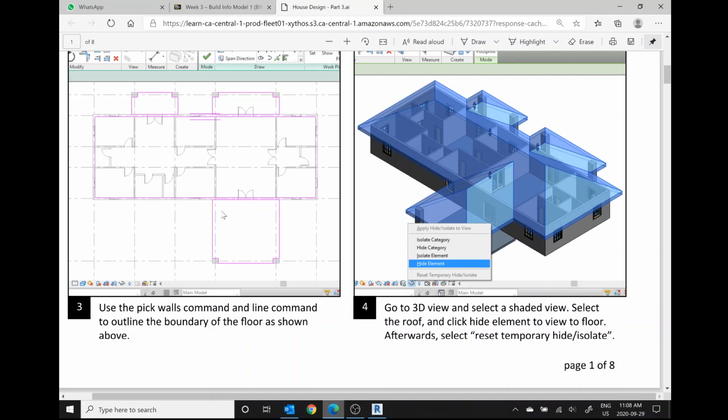Now from a construction point of view that makes sense, because the exterior ones are going to be subject to freeze-thaw cycles. So the ground is going to shift up or down a little bit based on how the water is freezing in the soil. And even if that's only 1 or 2 centimeters up or down, it's enough to crack concrete if it's attached to something that isn't moving. Even 1 or 2 millimeters of differential will create hairline cracks in concrete. So it's smart to separate them into separate floor plates. And so that's what we're going to do.